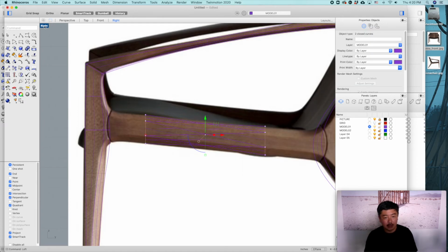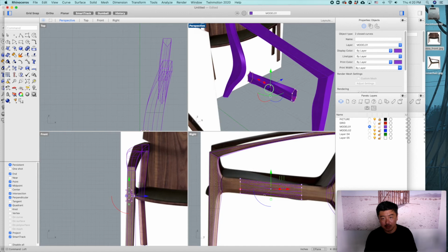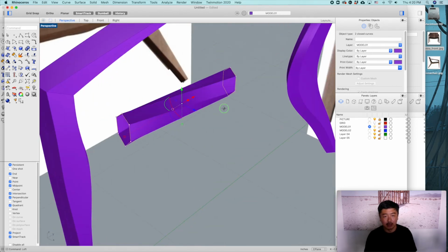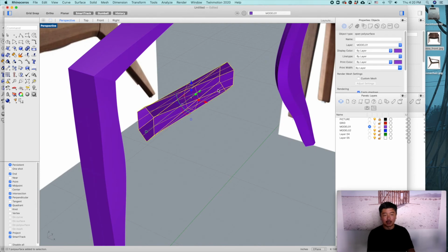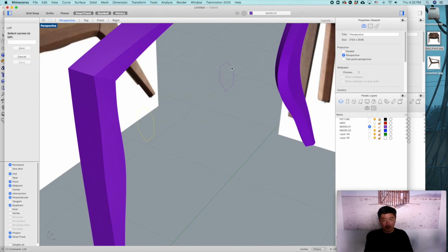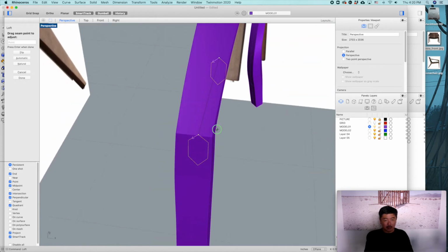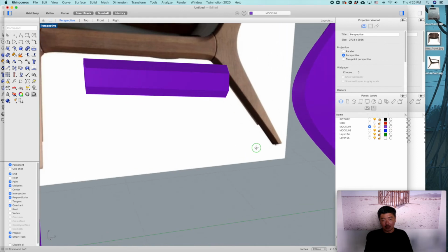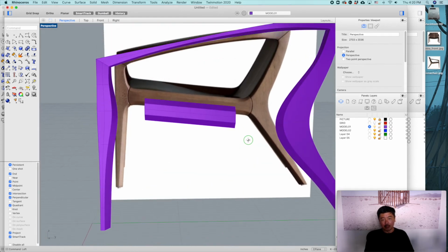And then this is an example of a bad seamed loft, okay? Because the seams are twisted, even though I just made a copy of the same object. So type loft, and then click on the same part, and then the seams are right, directions are right. And then that's when you can create this kind of clean loft.